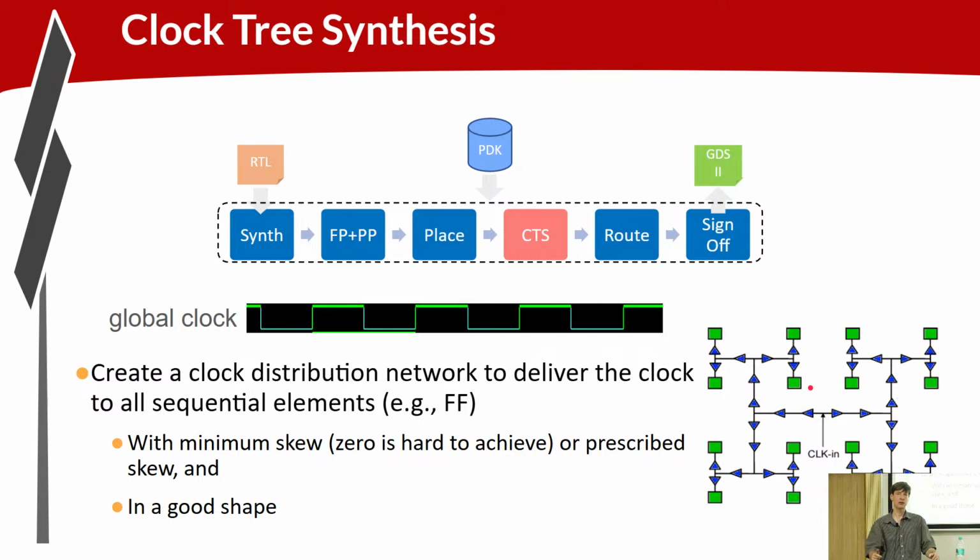So you've ensured that the two paths are close in length, but since they're different paths, they could still be a little bit skewed. The idea of the grid clock is basically to connect these two up. If there's a little bit of difference, maybe this one gets here first. If they're connected, the clock edge bleeds over this way. You can minimize skew that way further. So grid clock obviously is more of a grid than an H tree like this.